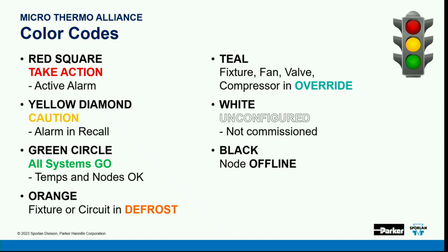But a truck comes in and he forgets to close the door and he starts unloading the truck. Now, even though that alarm is acknowledged, it's going to start counting down. Okay? And if that door remains open and never goes closed, then we're going to trip the recall period and we're going to send a new alarm out saying that the door is left open.